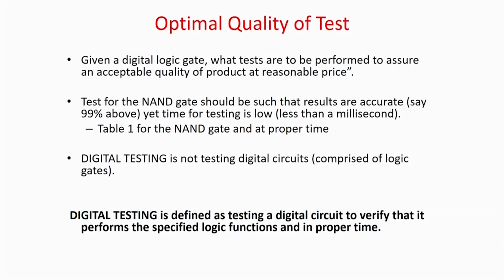So what are the basic paradigms, or what do I basically require for test? Many people say that we require 99% plus fault coverage or guarantee. We will tell you about fault coverage. I give more than 99% guarantee that whatever I send you as a proper chip is correct. That means out of 100 chips you manufacture, 30 may have defects, that is a yield problem. But when I say 99% accuracy, it means that if I am sending some 70 chips, there is 99% probability that whatever I am sending as a proper chip should not have any manufacturing defect. That is the idea.